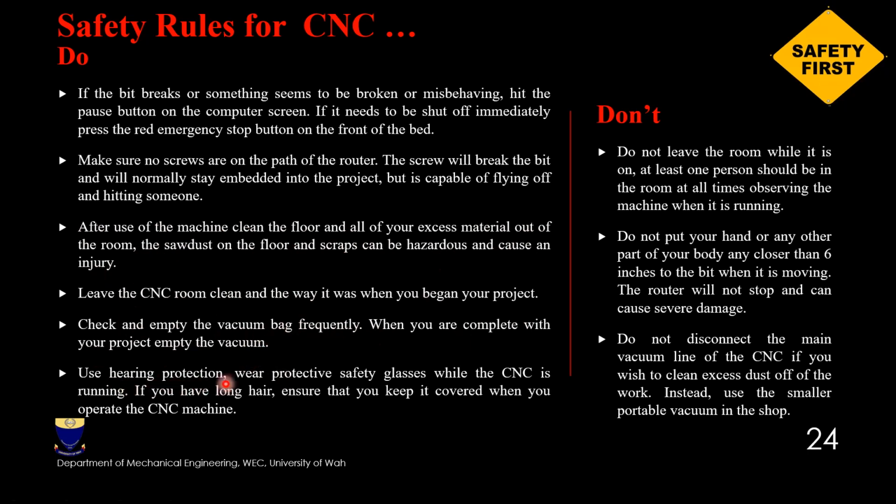Use hearing protection, and wear safety glasses as well while the CNC is running. If you have long hair, ensure that you keep it covered when you operate the CNC machine. This is for the female staff or the boys who have long hair as well. Do not leave the room while it is on. At least one person should be there at all times observing that the machine is running correctly.